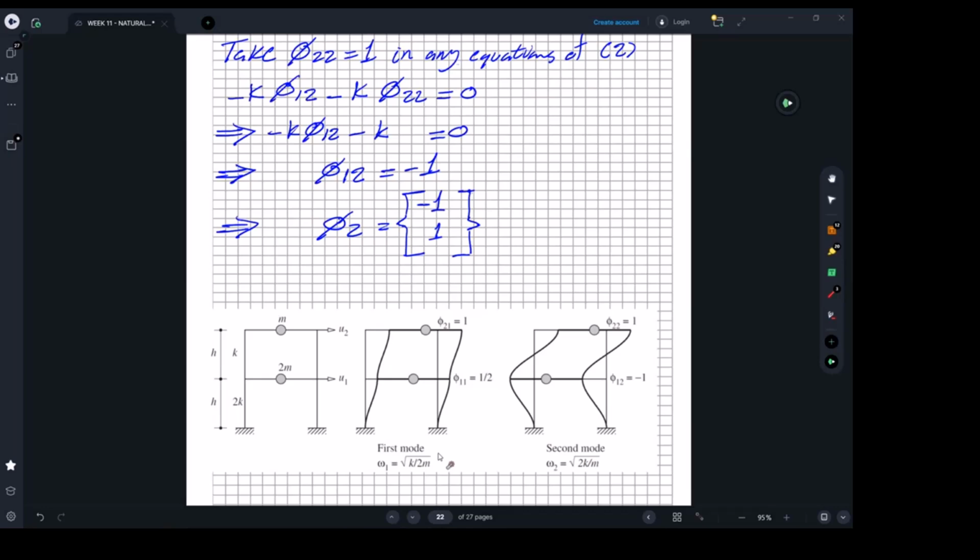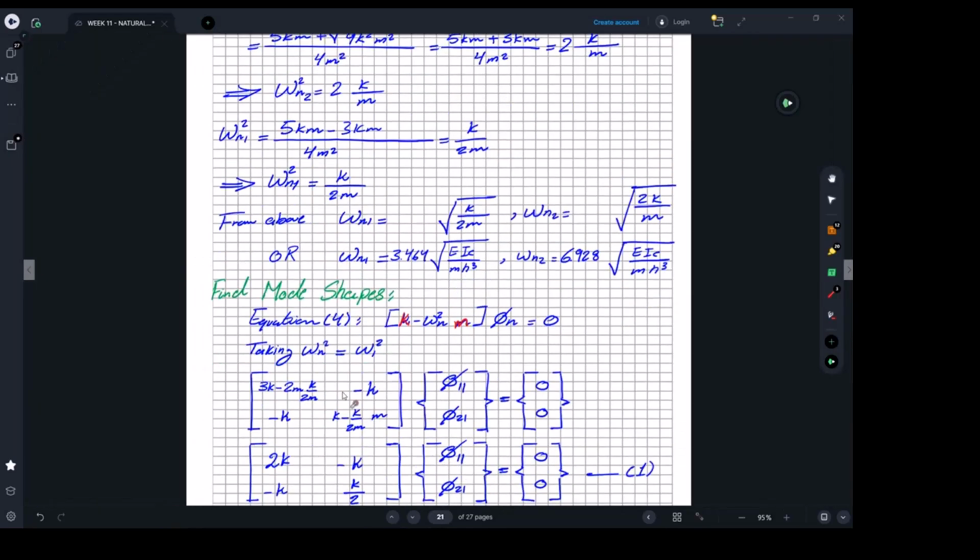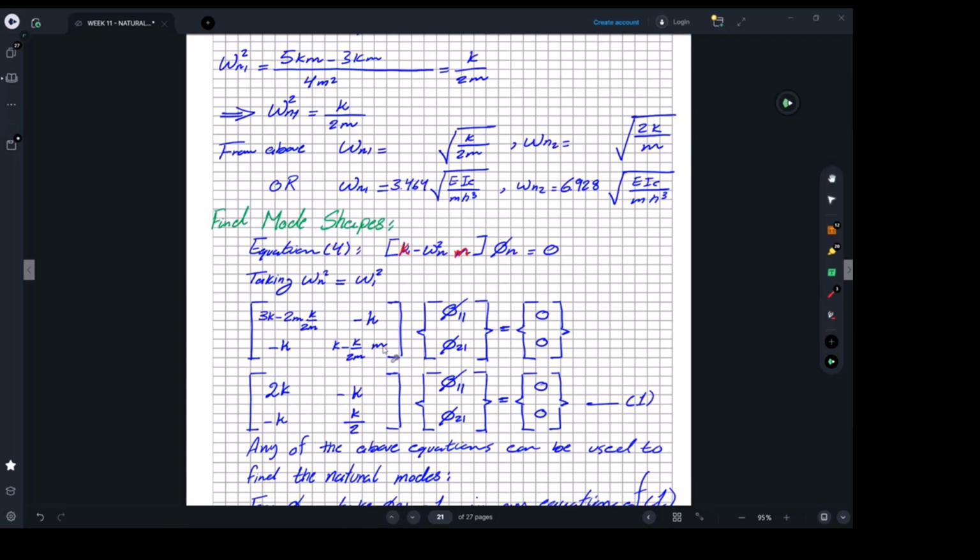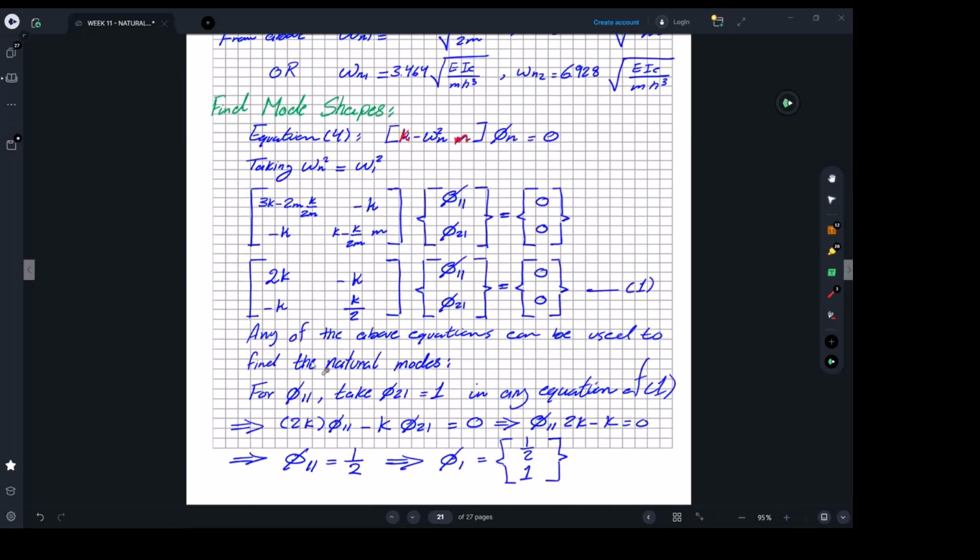So if you find in your multi-degree of freedom system that it is resonating with the exciting force, then you just play with the stiffness usually to get it to work. So, any questions?